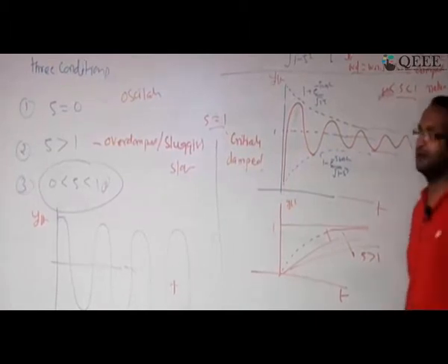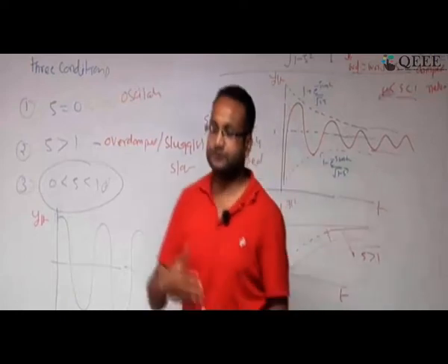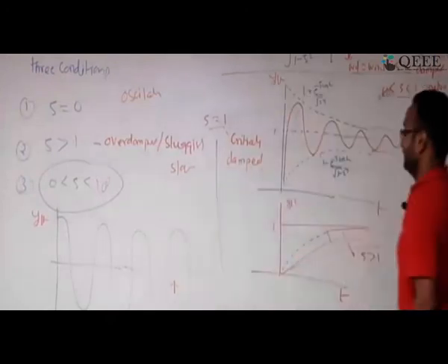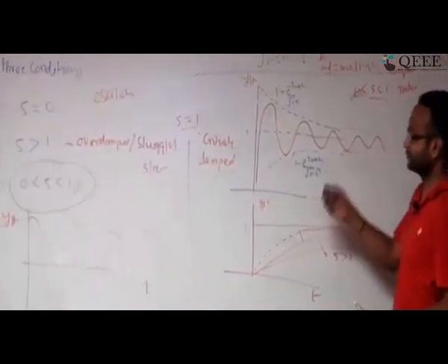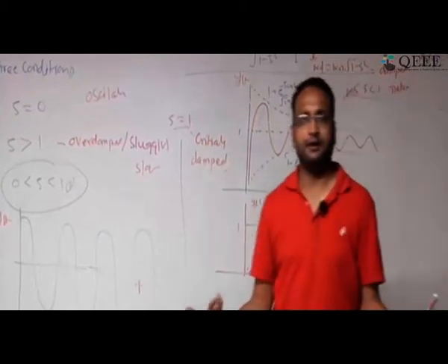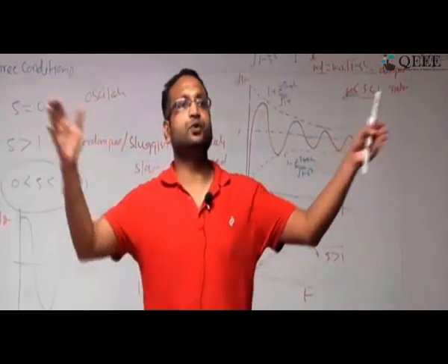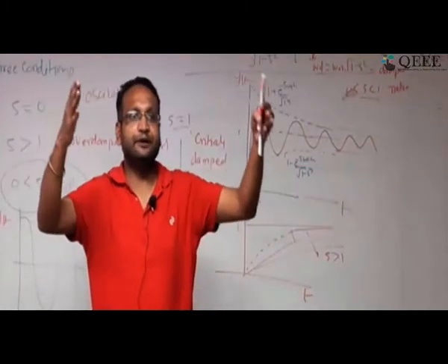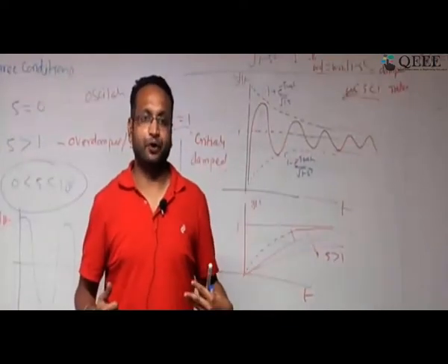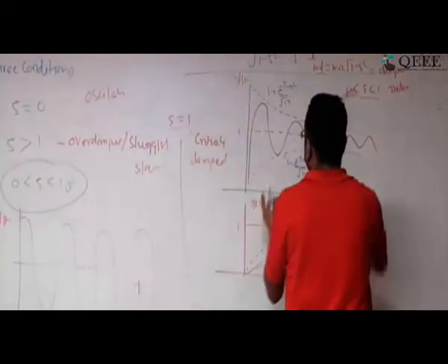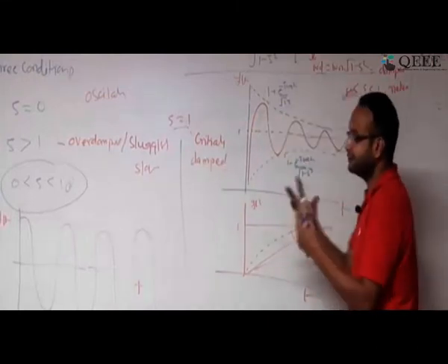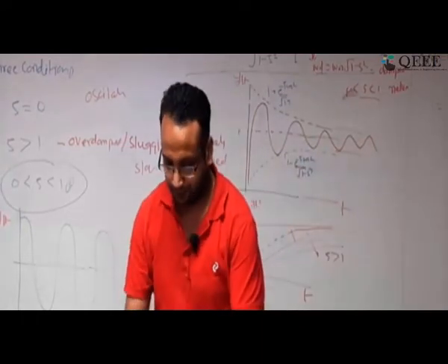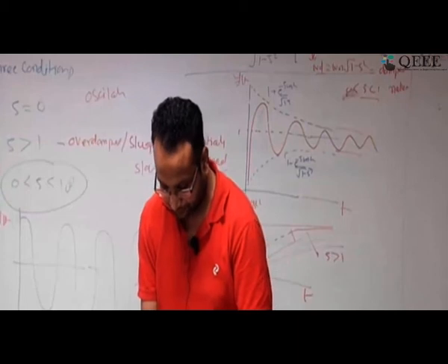Okay. So as I mentioned in the case of the first order system, your time constant has to be smaller and smaller to make your system fast. How do I say the same thing here? When I am saying what is desirable, should I use zeta equal to 0.2, 0.3, 0.5? It will keep on going. As I mentioned, zeta range 0 to 1 is desirable. Beyond 0 is desirable, beyond 1 is not desirable. It is desirable between these two. So, what is the optimal value? Okay. For that, we will be quantifying this behavior using some parameters. Okay. And those terms I am going to write now. Okay. Fine.